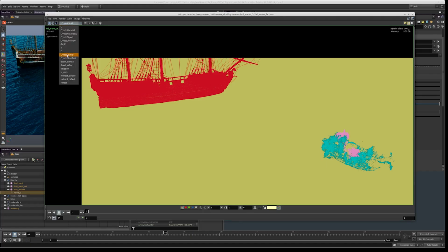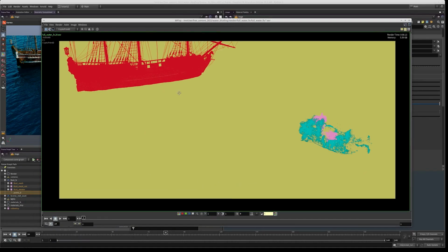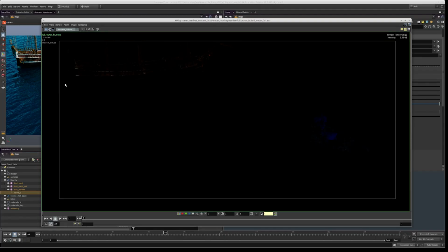I think this name can be anything you want, but the most important thing is that you have to tell it which string to look at, and then you have to toggle the Cryptomatte attribute option to make sure that this is treated as Cryptomatte, because it has to save data differently. And then all the other passes are there.